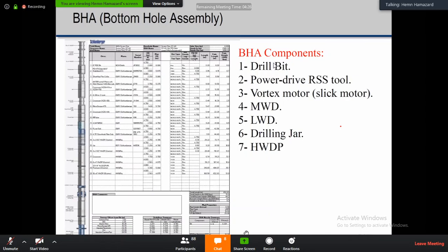Instead of KCl or any salt, we need to put cement, and the cement height in the well can be calculated easily. Above that, yes, it can be salt, it can be mud, anything like that. And mud is cheap. If you abandon a well after spending millions of dollars, you can put about $2,000 worth of mud in the hole just for environmental concerns.